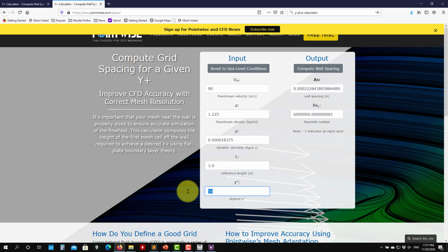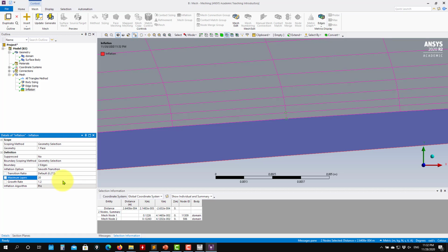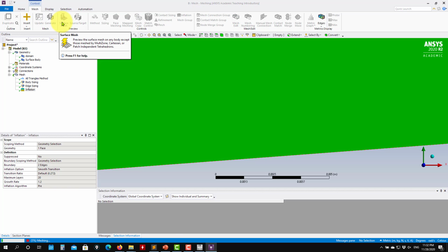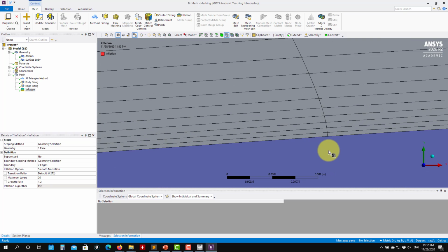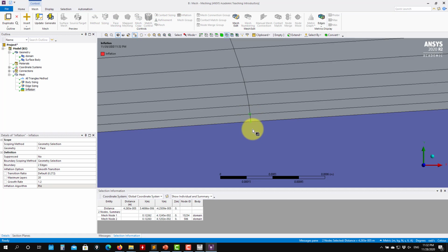It still is okay. Important, it needs to be close to 60. In our case, it's something about that. So see that you can measure. If you want to have this cell closer, basically what you need to do is increase this one. You will see that I put 20 there, and if I generate, see that now everything is closer, and now you can measure from here to here. Control, and see that you have this distance that is probably closer to Y+ values around 1. In our case, let's leave it here at 10.